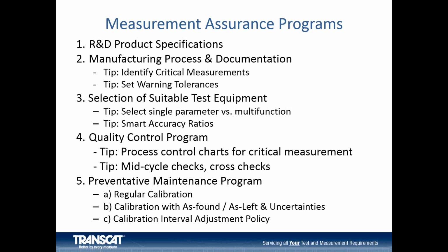They planned it. One other recommendation I would have is single parameter test equipment versus multifunction test equipment. The little example I went through here is a single range, single purpose device. If I had a multimeter which can measure AC volts, DC current, resistance, temperature, SPRTs, thermocouples, and you have an out of tolerance condition on any one of those things, you need to do an investigation.